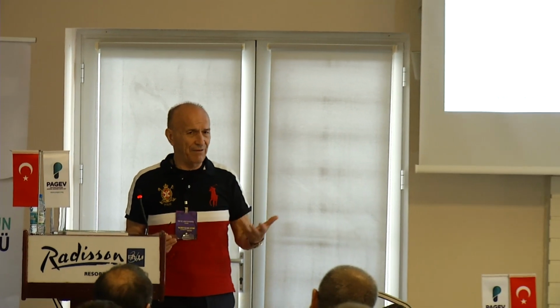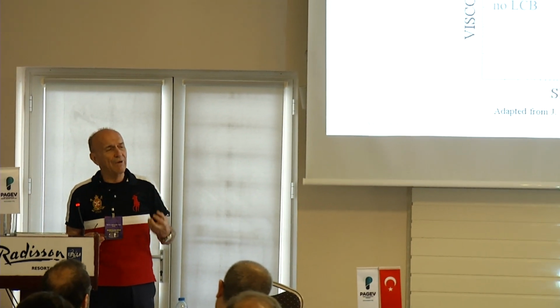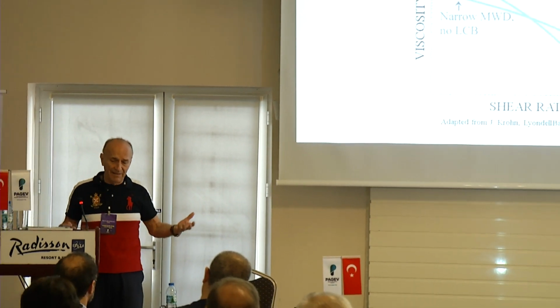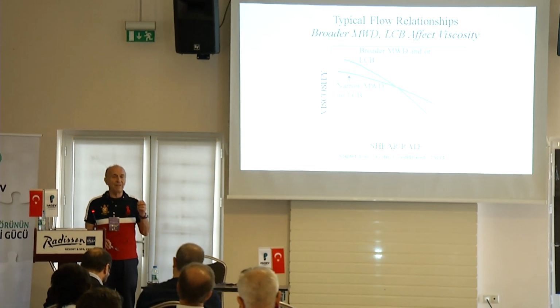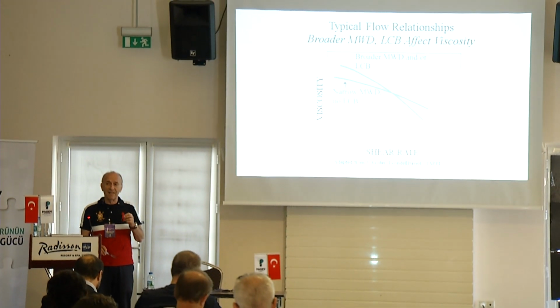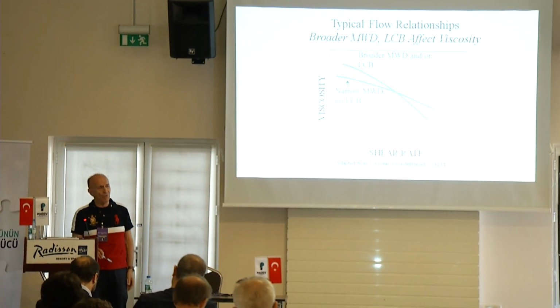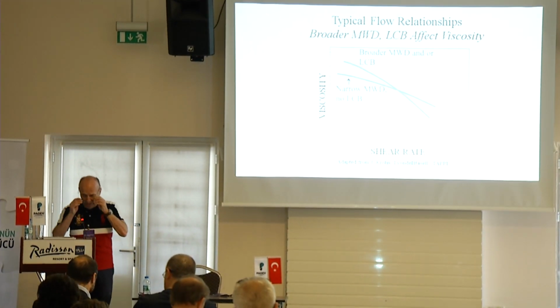Temperatures easily drop to minus 20, and where I live, in Toronto, the record temperature is minus 30, and of course, snow and rain and whatever, a very difficult environment. So they had to withstand it, and by having products with melt index less than 12, it was always working, so the problem was solved.